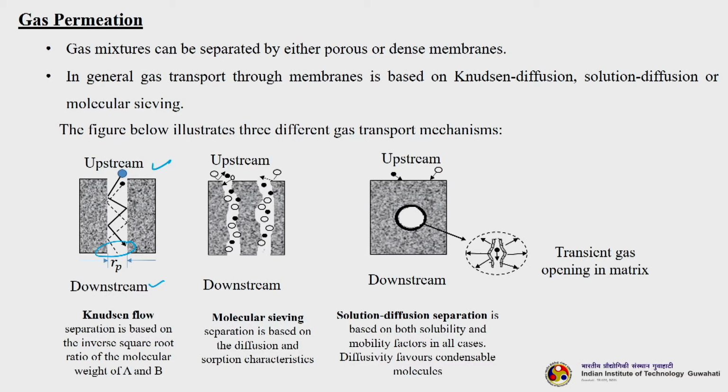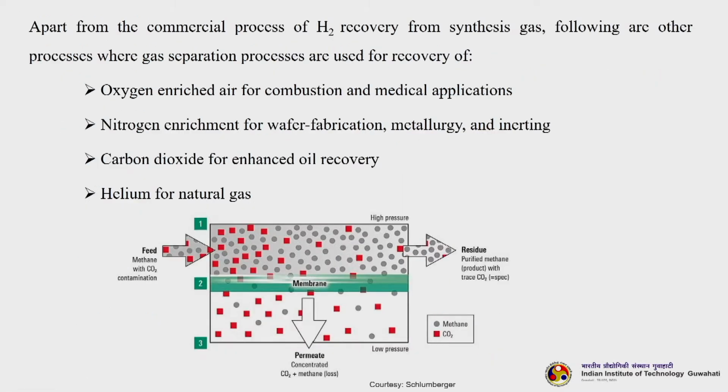The next one is solution diffusion separation, as you understand from the name. The separation is based on both the solubility as well as the diffusivity of the solutes. Gas separation has many applications. One of the most important commercial applications is hydrogen recovery from synthesis gas. Then oxygen enriched air for combustion and medical applications, nitrogen enrichment for wafer fabrication, metallurgy and other applications, carbon dioxide for enhanced oil recovery, removal of carbon dioxide, then helium from natural gas.